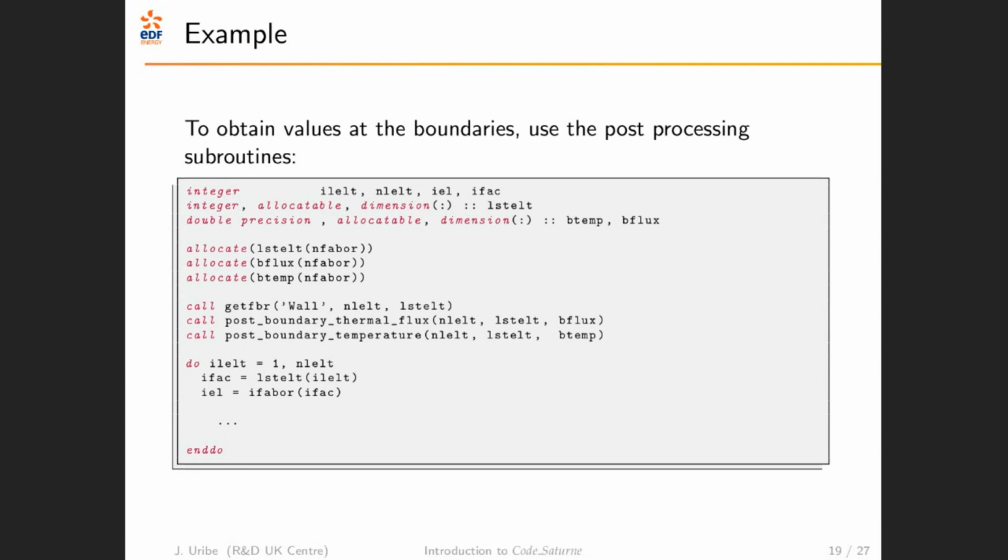I also added in the chat that some arrays, which is not visible in the Fortran part but in the C part, are defined as 32 bits. Those are mainly the boundary condition arrays. The cell ones are usually defined in 64 bits, because when you have meshes of, let's say, 200 to 300 million cells, the connectivity between the faces and the cells can be over 2 billion, which is actually the limit for 32 bits.